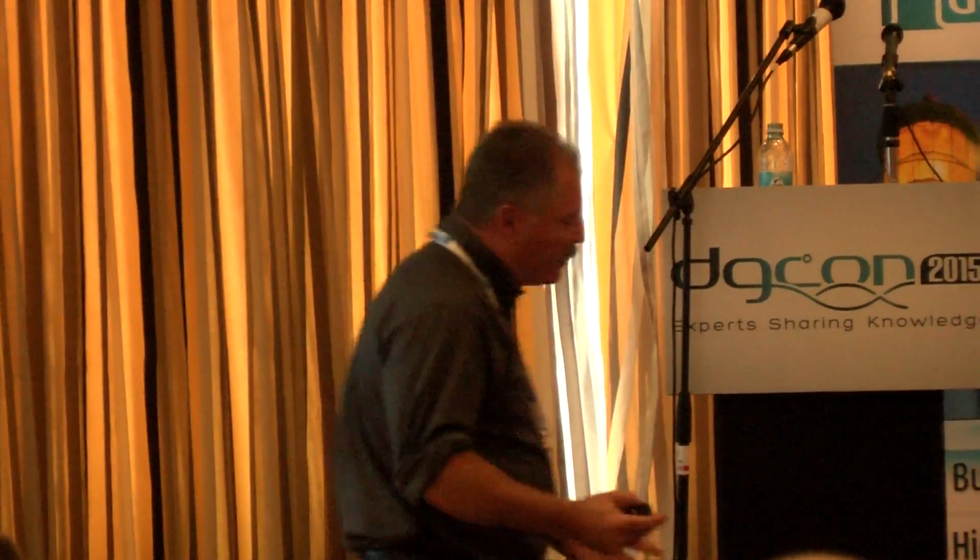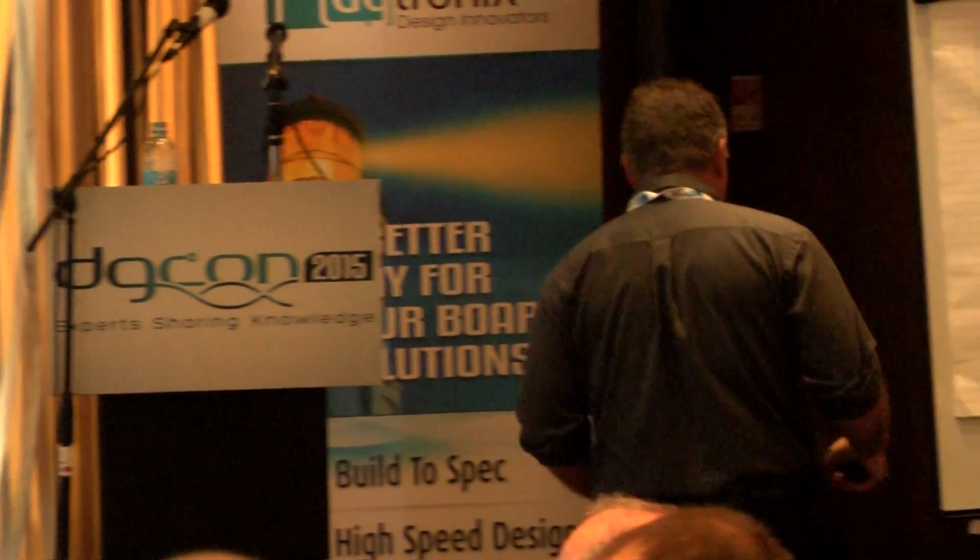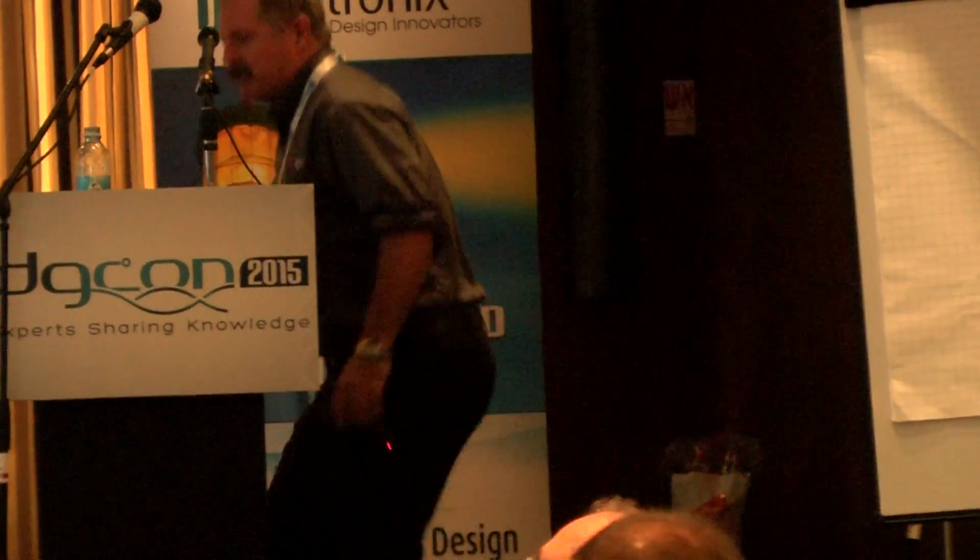Either way, the 1x is easy to try, and when you get down to the details, this is really nothing when you're talking about high-speed digital. So again, the idea is try the 1x AFR method because it's easy and quick to try. So that was comparing everything to simulation. Let's take a look at measurements of different structures.